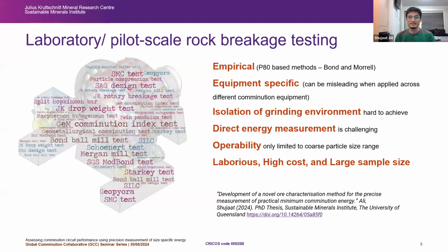Also, direct energy measurement is extremely challenging. It can happen at the coarse particle size range if you use some compression test or something that I'm going to talk about further on. But the applicability of a single method to cater for all these requirements that we need is so hard, and it doesn't exist, right? And on top of that, other things are there: extremely laborious, expensive, and large sample sizes are needed. I'm talking about, for example, the drop weight test, 200 kilograms per sample.